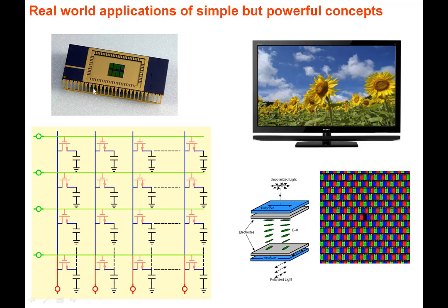One is a DRAM, dynamic RAM. Everybody is using it; my cell phone has 4 GB RAM and my laptop has 8 GB RAM. Everybody is talking about these RAMs, and everybody wants a lot of memory. These memories are DRAMs. If we go inside the dynamic RAM, how do I get a memory? The memory is a basic simple capacitor. When I'm talking about a capacitor, fine, C is dq by dv, and I equals C dv by dt and all that we talk about. But a very important point is that the capacitor is a memory element. In all your cell phones and laptops, one of the basic memory elements is the capacitor.